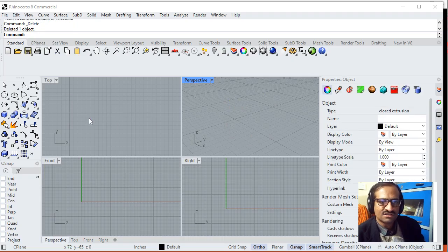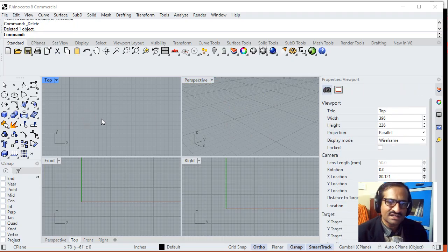I delete it. So now when I say 3 feet, can I enter 3 feet here? No, if I enter 3, it will not take it as feet, it will take it as inches. So if I have to type 3 feet, then I have got two ways. One is I will type 3, then I will type the symbol of feet, the keyboard symbol which is to the left side of your enter button. So if I am typing 3, I have to accompany it by this feet.